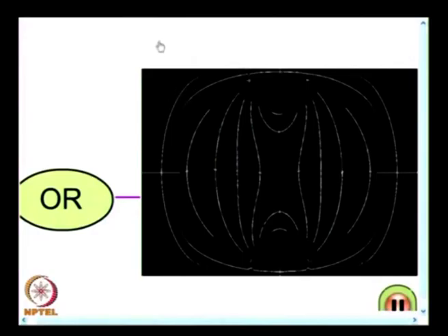So, what you find is, scan the image horizontally and vertically, each scan provides you some fringe points and some noise, and a logical operator helps you to connect all the fringe points. All the fringe points are now collected, but you also have noise. If you go to another set of orthogonal scans, you are able to get all the fringe points, but with noise in a different direction. So, when I do the logical AND, the noise is eliminated. That is the principle behind it.